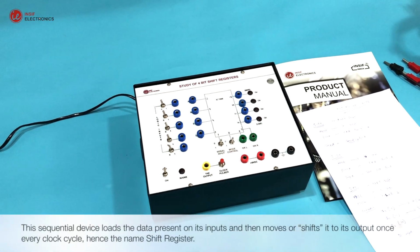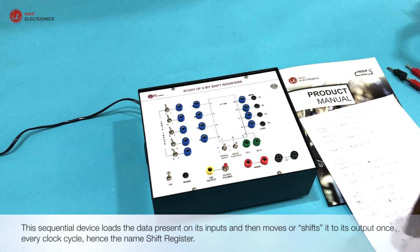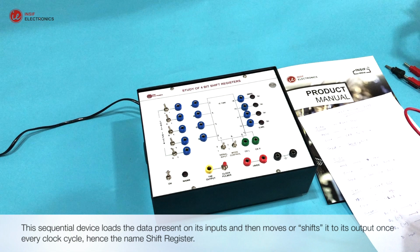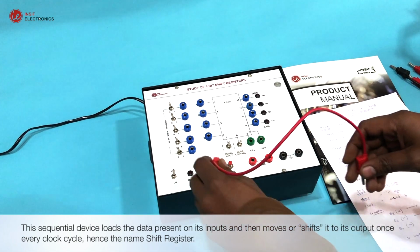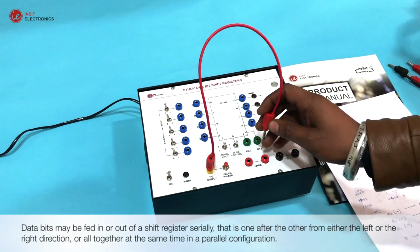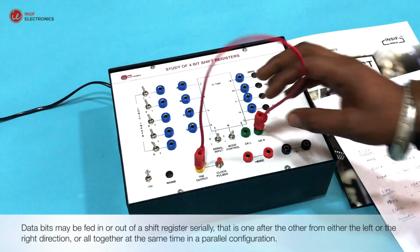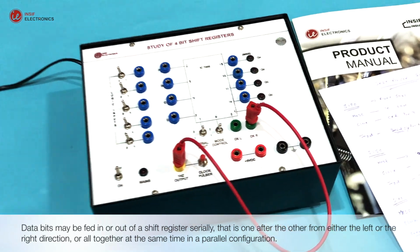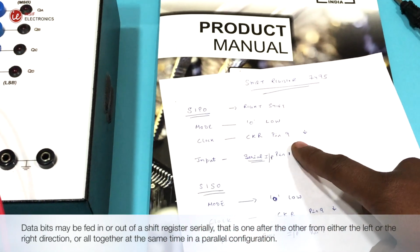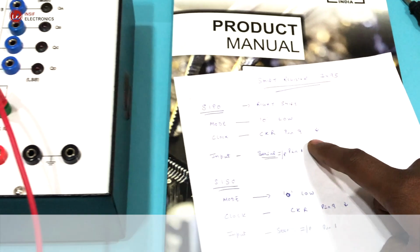This sequential device loads the data present on its inputs, and then moves or shifts it to its output once every clock cycle, hence the name shift register. Data bits may be fed in or out of a shift register serially, that is one after the other, from either the left or the right direction, or all together at the same time in a parallel configuration.